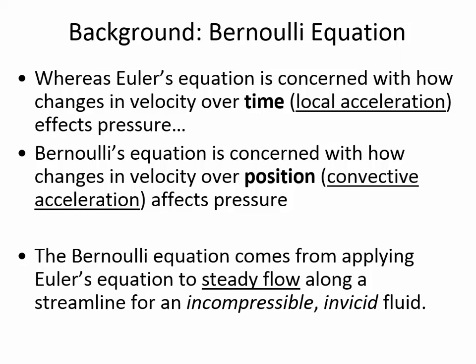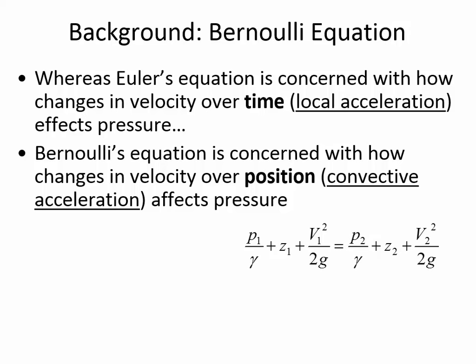So here we have a series of assumptions actually that can never be strictly true. That's one of the weaknesses of Bernoulli's equation, that it's this theoretical equation that actually is never going to be true, because we're saying between 2 points there's no energy loss, and there's always going to be some energy loss when water flows between 2 points. Even if the 2 points are close together, like they are here in this drawing, even if they're just half a meter apart, as the water flows from one point to another, the pipe is going to be resisting flow. And as the pipe resists the flow, there's some fluid drag, and that's reducing the pressure in the direction of flow because of the energy loss.